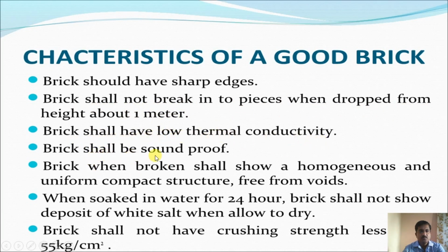Brick shall be soundproof. Brick when broken shall show a homogeneous and uniform compact structure free from voids. When soaked in water for 24 hours, brick shall not show deposit of white salt when allowed to dry. Brick shall not have crushing strength less than 55 kg per square centimeter.